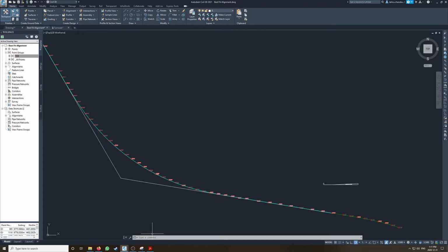I will, however, use the Transport Canada design standard for track center and track clearances just as a starting point. And I'm going to use a number 20 turnout as my turnout for the siding track.